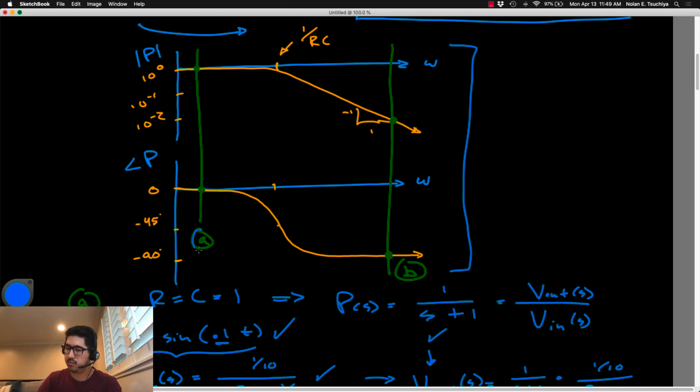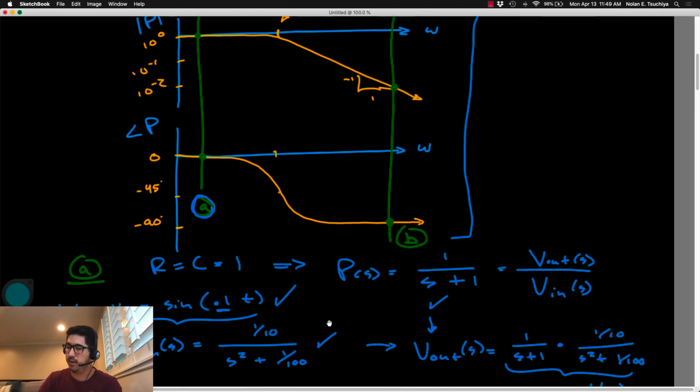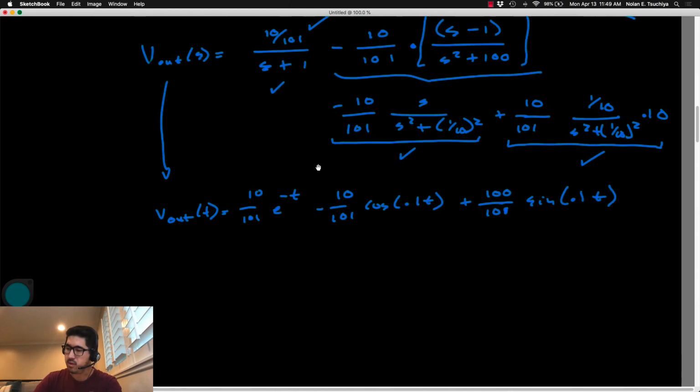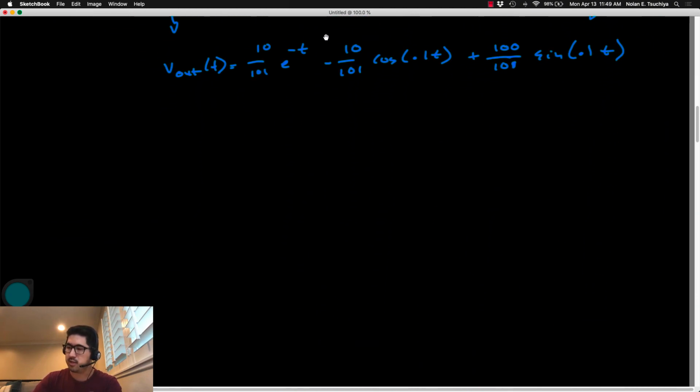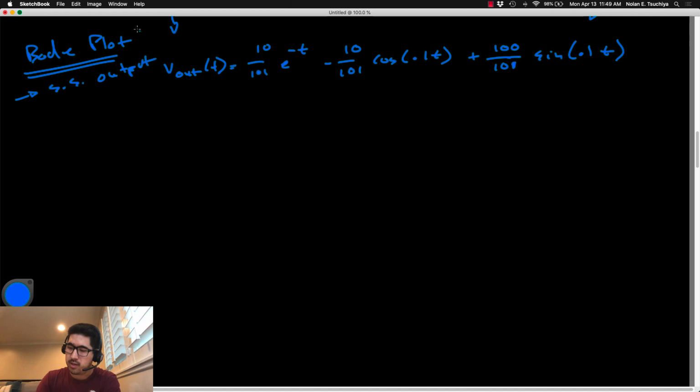We're looking at, again, frequency A here. A low frequency should pass through the filter if it's a low-pass filter. So how do we make sense of this? Well, the first thing to note is that the frequency response plots, in other words the Bode plots, tell us about the steady state output, which is, as we know, what is left over once all the transients have decayed. That's what the Bode plot tells us.